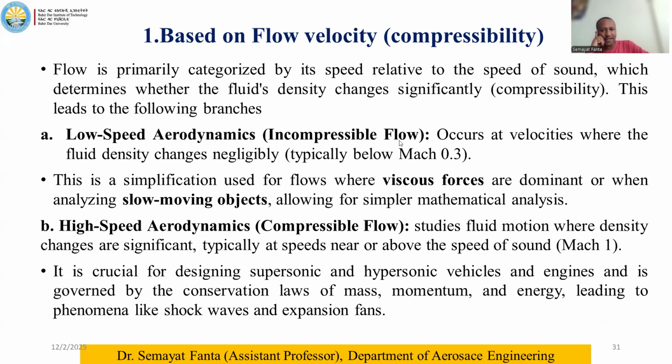Mach number is just a non-dimensional aerodynamic number, which is the ratio of object speed, or particularly aircraft speed, divided by the speed of sound. And as you know, the speed of sound depends on temperature, pressure, and density, or altitude. Why?